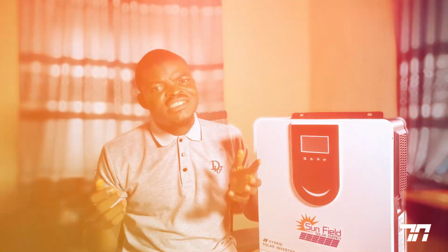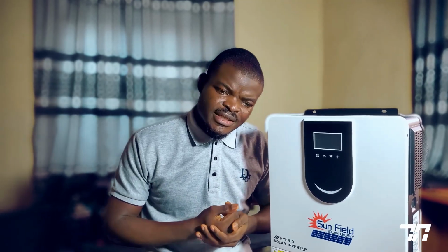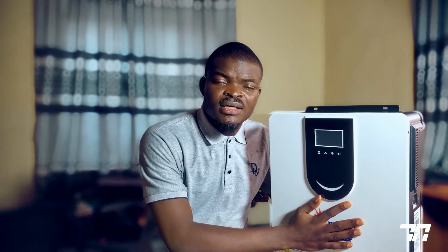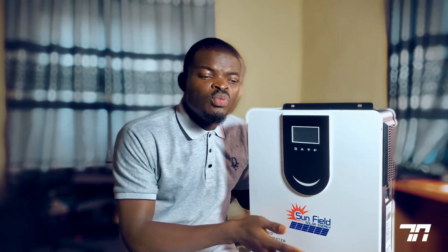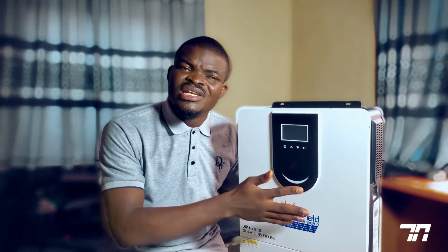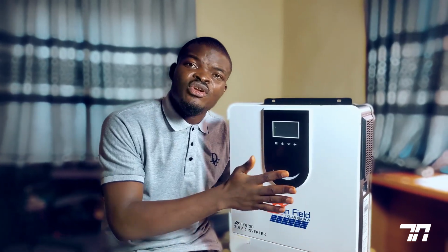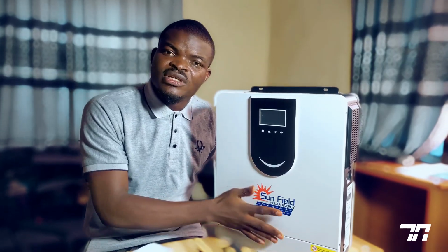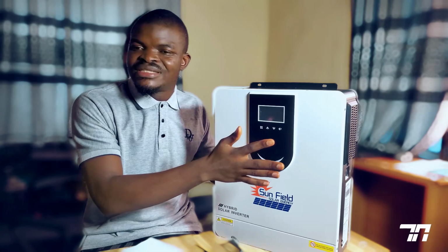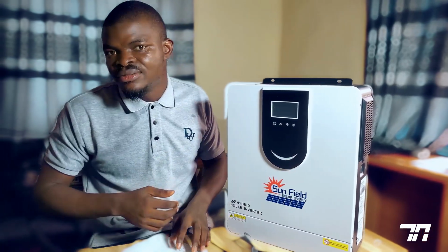So let's look at the common mistakes most of us installers used to make when dealing with high frequency inverters. Now, unlike low frequency inverters, a high frequency inverter, whenever you are installing it, is a programmable inverter, and once you finish installing it, you have to do the necessary programming, which is what most people used to leave out. And when you do that, the inverter cannot function to its full capacity. You have to set those parameters for the inverter to perform up to its maybe 95% efficiency.